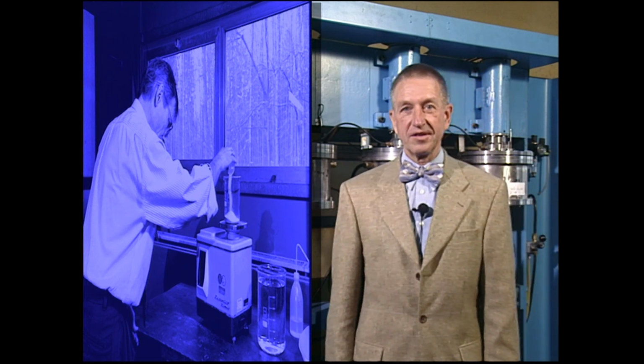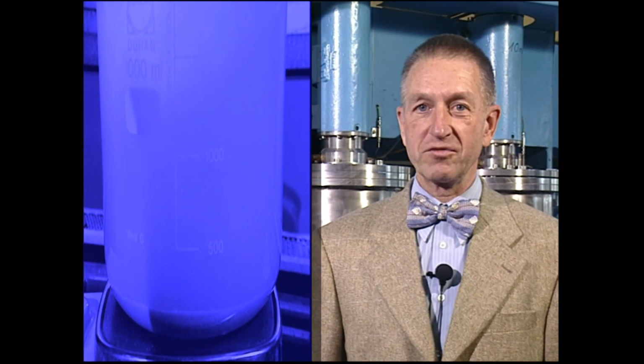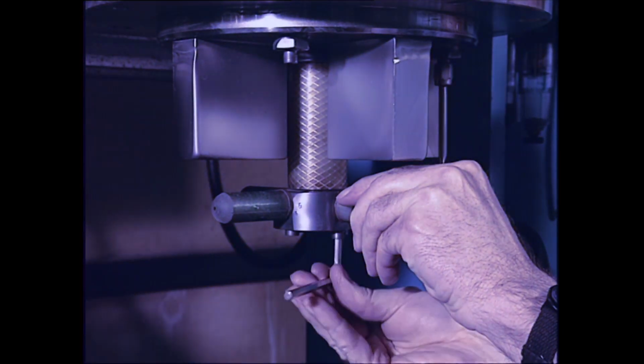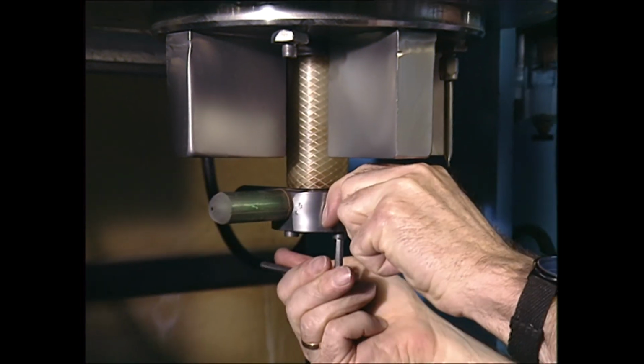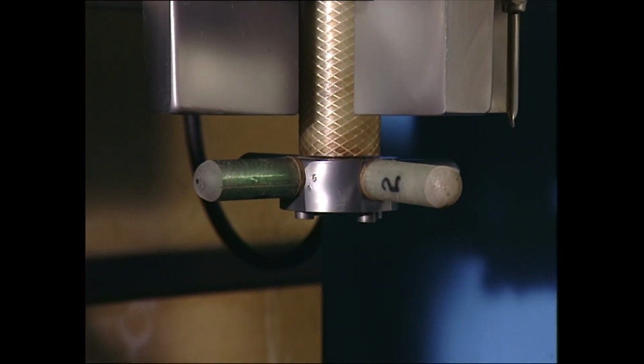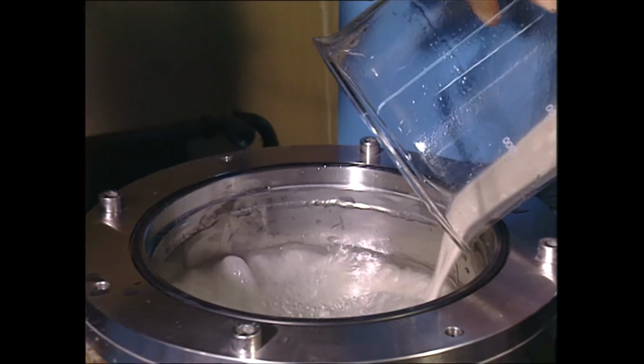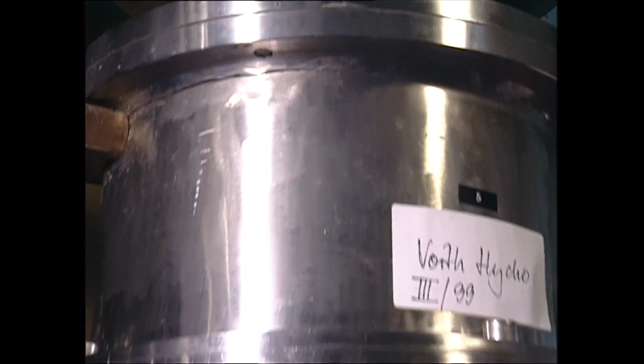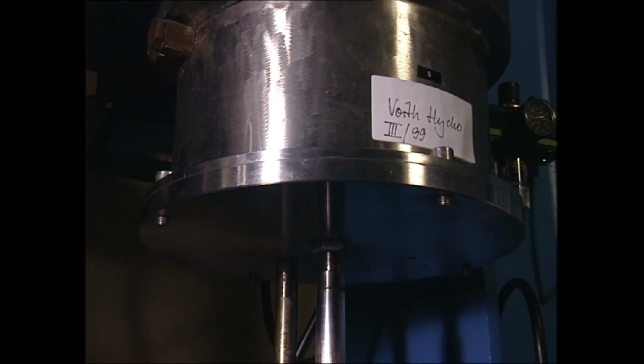Modern technology provides a variety of different methods to cope with wear. However, the hydroabrasive wear, as it occurs in water turbines, is a very specific kind of wear and needs very careful qualification of materials. The slurry pot test, for example. Cylindrical test bodies are fixed on a shaft which rotates in a clearly defined sand-water mixture. After a certain period, the mass loss of the test bodies characterizes their abrasion resistance.